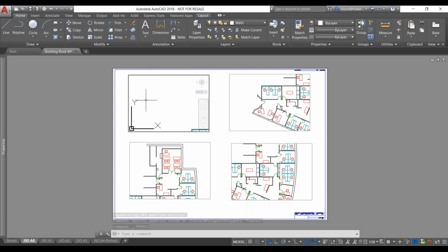So if you want to cycle through some of the viewports, what I'm going to do is enter the viewport I'm clicking on, holding Control and using the letter R on my keyboard. Whilst holding Control, hitting my R button and cycling through the different viewports on my sheet. It might be a quick way to just jump in and out of viewports, instead of exiting, going back into there, and so on and so forth. A nice time saver that you might want to remember and use. All right.